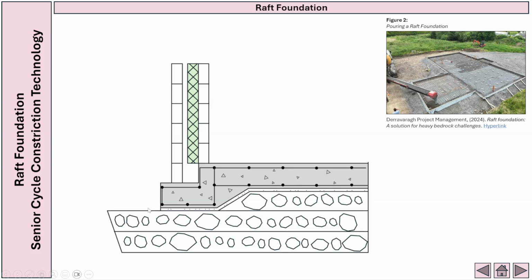Next, we're going to fill in our hardcore, and these sections here are 150mm each, totaling 450mm. Over to this section here, we just came out about 400mm and then brought it down 60 degrees here.